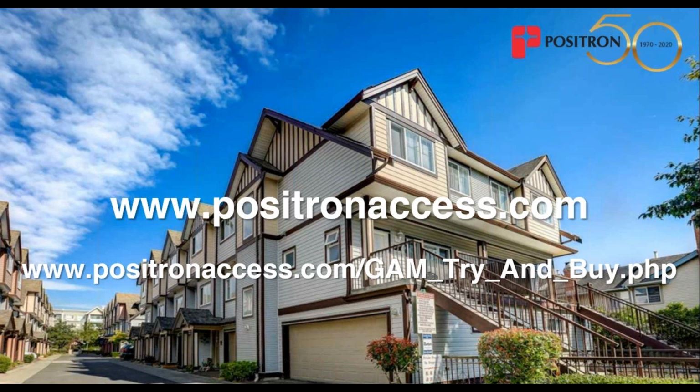Thank you, Pierre. In coax mode, do you support satellite TV? Yes, we do. We can do either DirecTV or Dish. And the way this is done is the output of the SWiM, the single wire modules that feed one subscriber at a time. We take the output of that, we take a G.hn feed that may have already gone through splitters, and then we use a standard diplexer. So one leg is the satellite feed, the other leg is G.hn. It comes out on a single coax that enters the building.